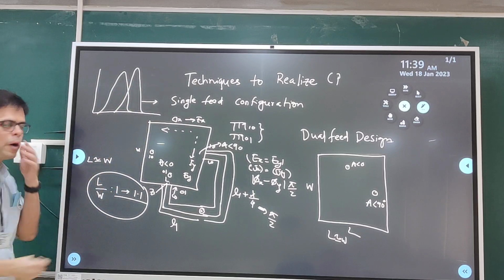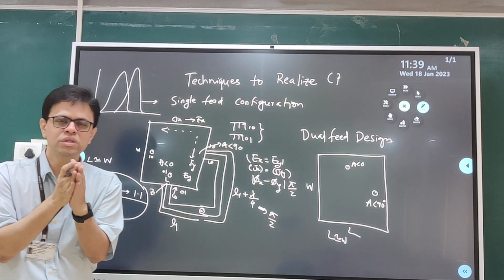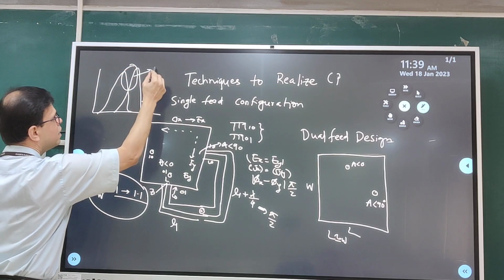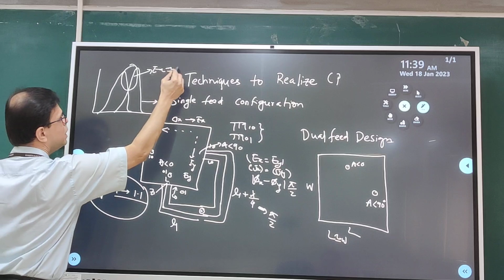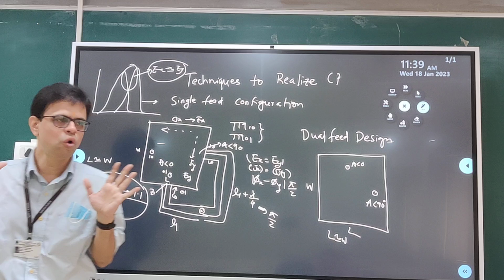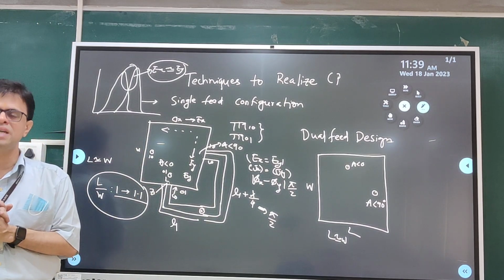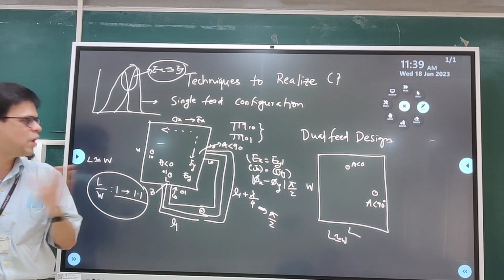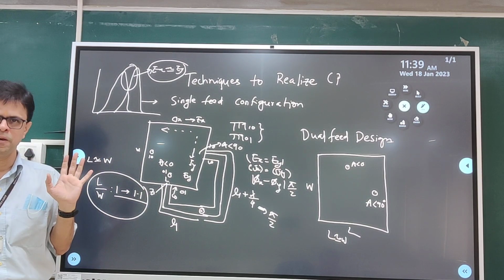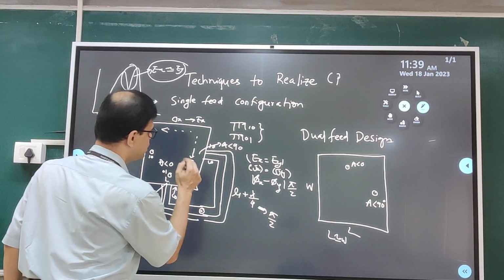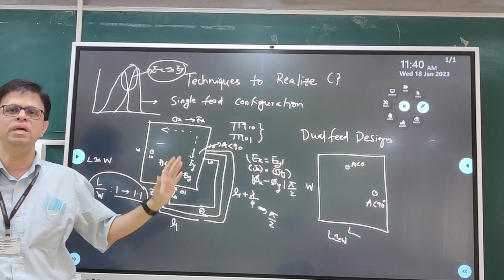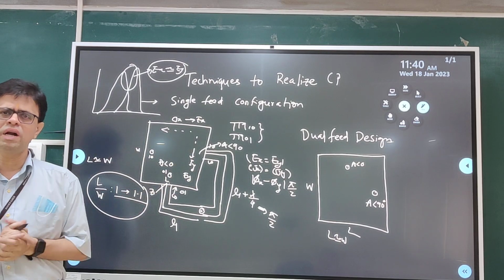If you plot the resonance plot, the two frequencies will be closely spaced, so in this region you will get Ex approximately equal to Ey. So all these three conditions are being satisfied at resonance in the rectangular microstrip antenna to ensure circular polarized radiation. These three conditions, this antenna design along with the power divider circuit, will give me a circular polarized radiation.